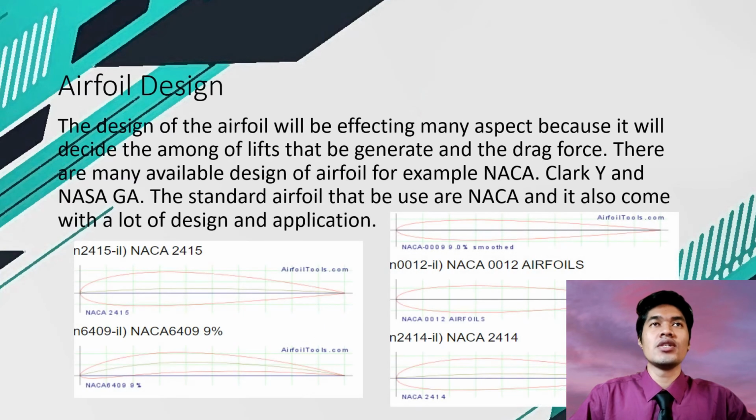So next is the study on the airfoil design. The design of the airfoil has many aspects, because it will decide the amount of lift that is generated and the drag force. There are many available airfoil designs, for example NACA, Clark Y, and NASA. The standard airfoil that will be used is basically a NACA, and it also comes with a lot of designs and applications. Below is a list of some of the airfoils from NACA designs.